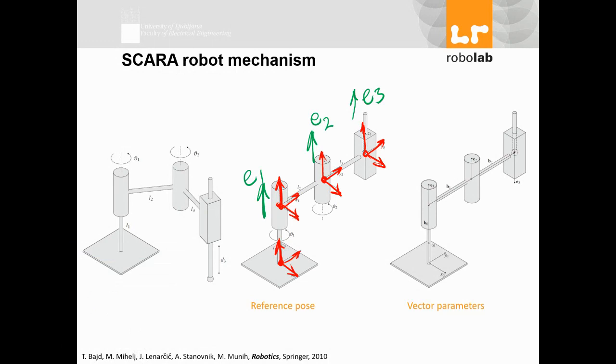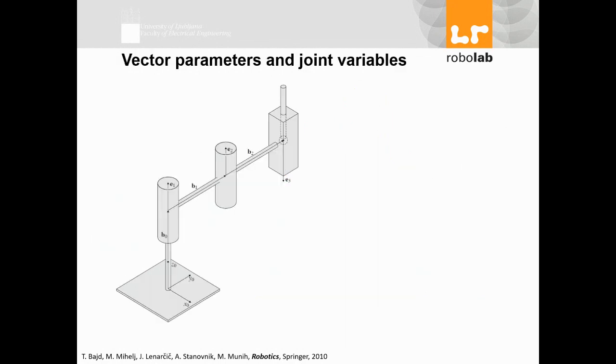Okay, and I have sizes and I have everything else. Now I write matrices for variable, for E, and for B. Three tables, not matrices. Table for variables, which here I have only theta 1. For this one, I have theta 2. For this one, I have D3, the displacement. So theta 1, theta 2, D3. Three variables. So table number 1, variables: theta 1, theta 2, D3.